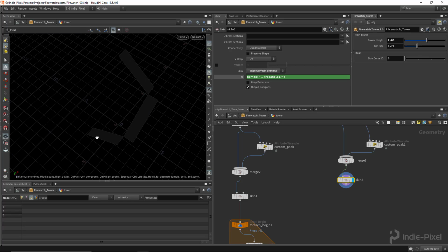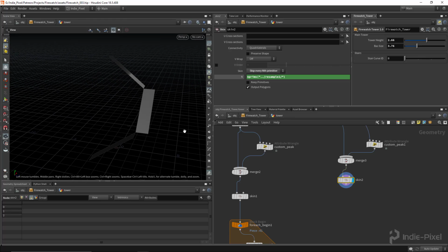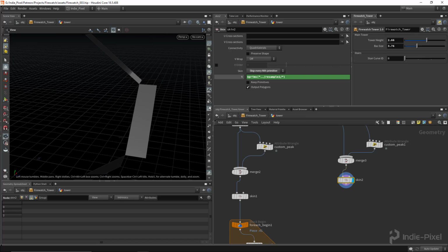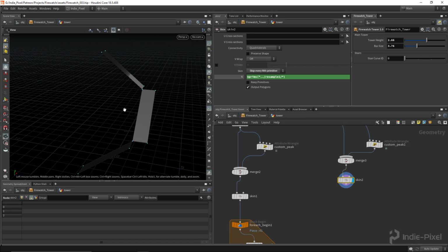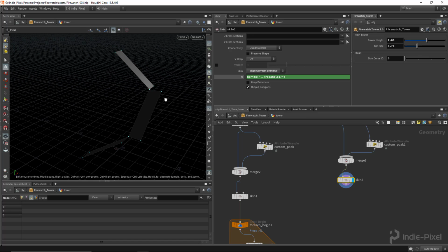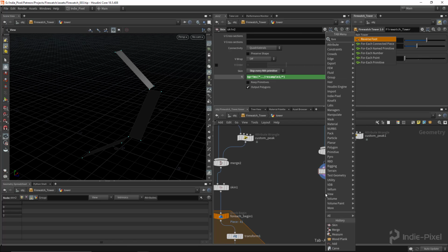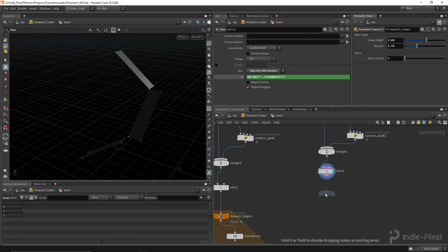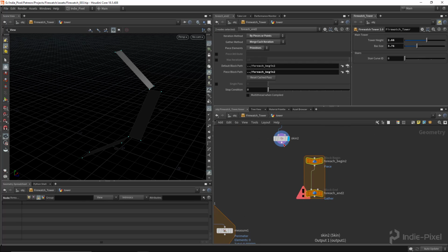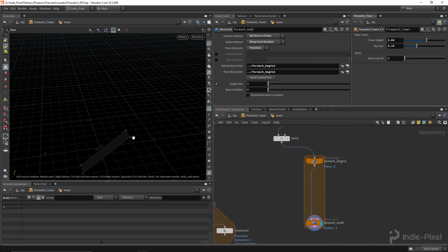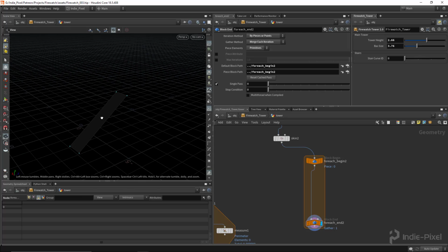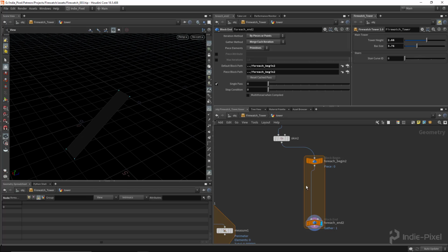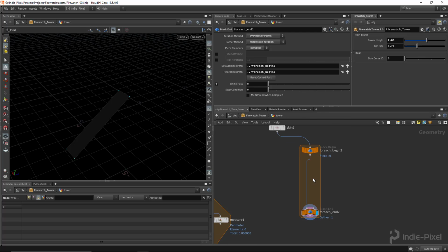There we go. So now we have 3 primitives, and specifically I am using this particular technique because I don't need all the resampled points. I just want solid primitives for this, so that I can loop through it. So we can do a for each primitive over here, and loop through each one of those guys and do a specific operation to create the platform at the top of each one of those particular stair steps there.